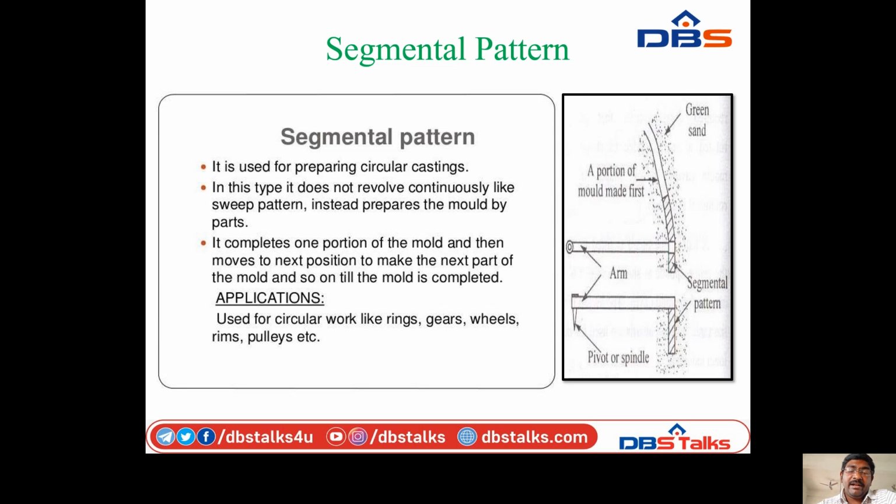A segmental pattern differs from the sweep pattern in that it does not require continuity. It completes one portion of the mold and then moves to the next portion to make the next part of the mold, and so on, until the mold is completed.